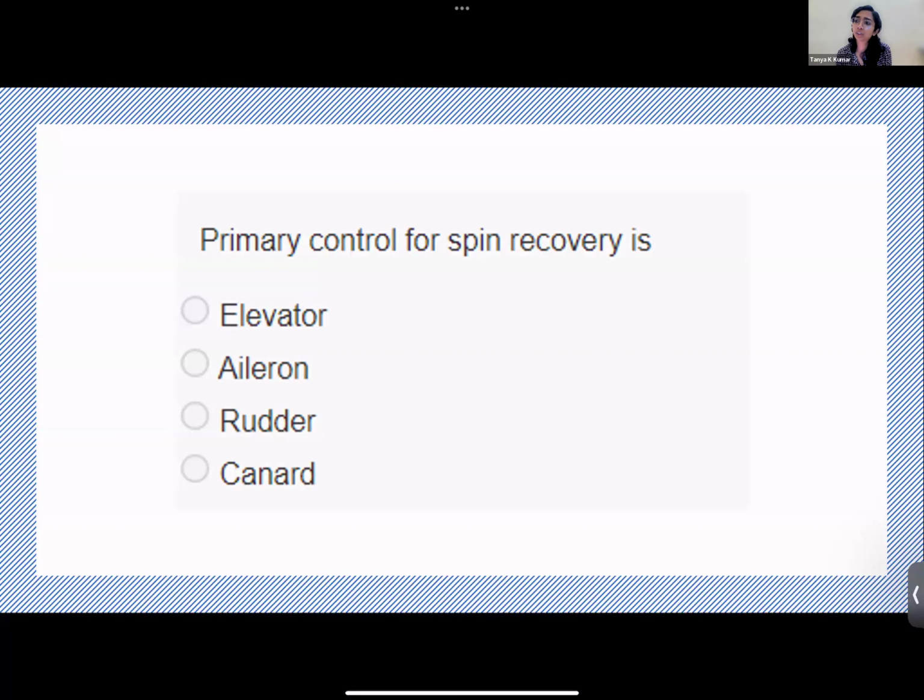Okay. So if it's not a propeller driven aircraft, what if it's a jet engine? What happens then? Suppose one engine fails and one engine is working, say the left side engine has failed and the right side engine is working, then the flight is moving toward the left side. We also control that movement to the left side. We raise the aileron on the left side and tilt the rudder on the left side, which goes opposite, by Newton's third law. I can't explain it better in English. Okay, but you were able to explain.